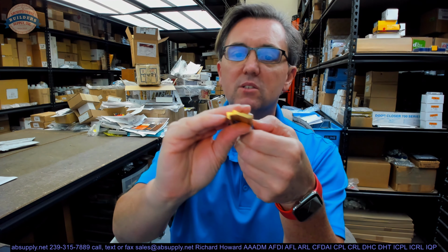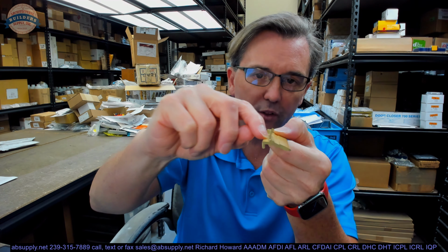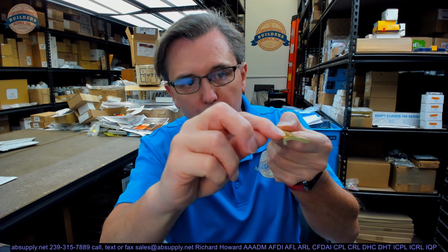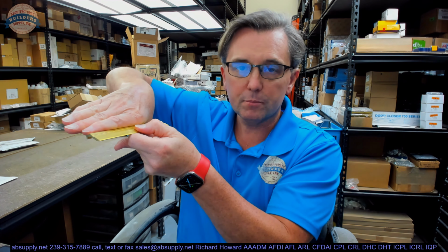So what that means is that you might have a saddle threshold. Well, the issue is that you have an offset flooring condition, and that offset flooring condition might be equal to the distance from the bottom of the elevator to where the lip of your threshold would sit. And in this case, it's probably a 1/4 inch. It is, indeed. So from the bottom here to where your threshold would sit would be a 1/4 inch. And that threshold would sit right inside of here and allow you to transition over that unusual floor condition. And that's what an elevator does.